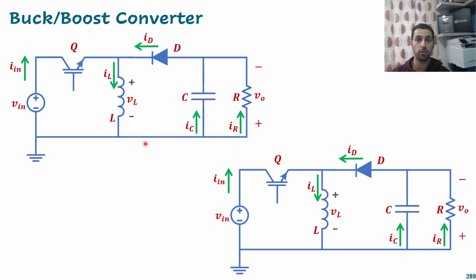So now let's start with two circuits. We will take the first one and analyze it in the on time, and the second one in the off time. During the on time, meaning the switch is turned on, we can convert it to a short circuit because we assume ideal switches. What will happen to the diode? V input travels to that node, which is the cathode of the diode, while the anode has a negative voltage, so we can assume the diode is off.